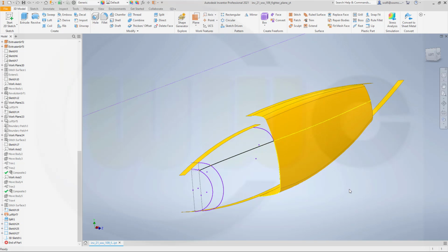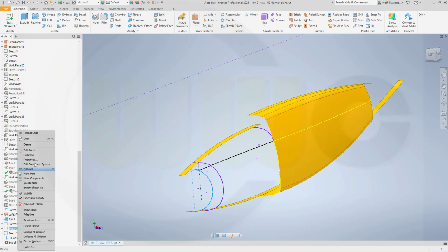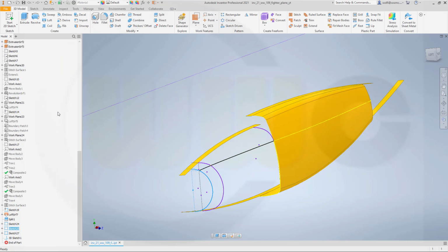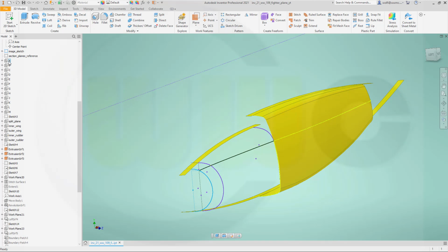And I wasn't sure, so I checked. I really can't select only parts of a sketch, so I need to copy those sketches. Let's start with sketch, this one. So go for copy and paste it onto the correct plane, which would be plane A. Paste it.